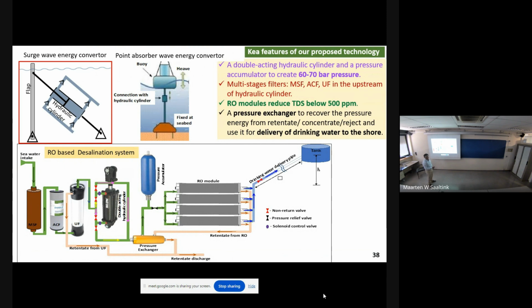But then you need some filters. Yes, filters will be needed. So there will be a lot of filters. So you use reverse osmosis. Exactly. But reverse osmosis is the last stage of the filtration. We have to filter using activated carbon filter, sand filter, all these things.